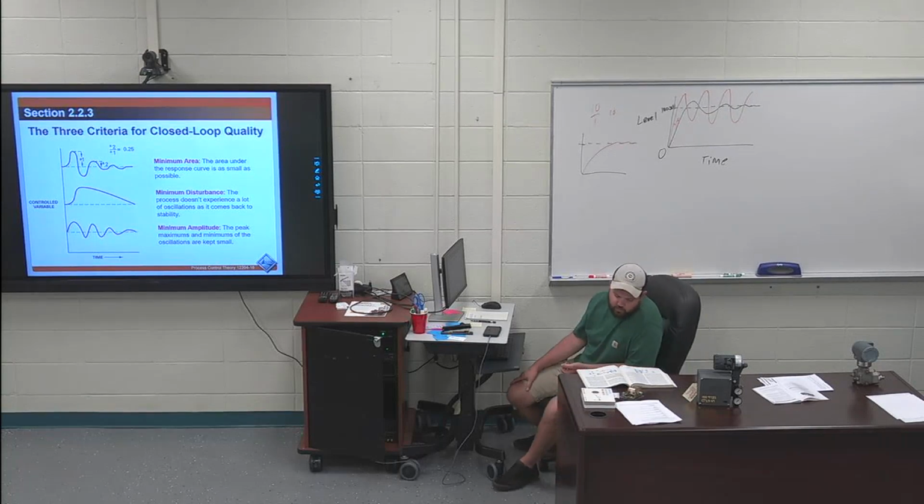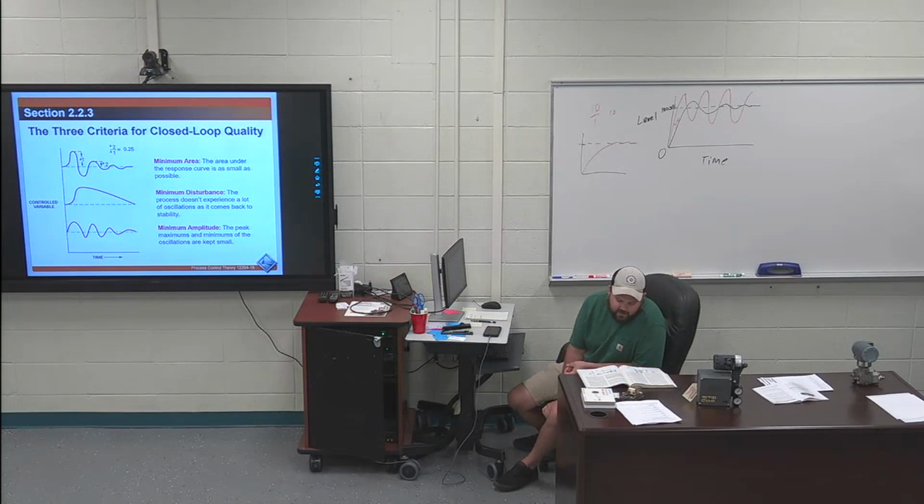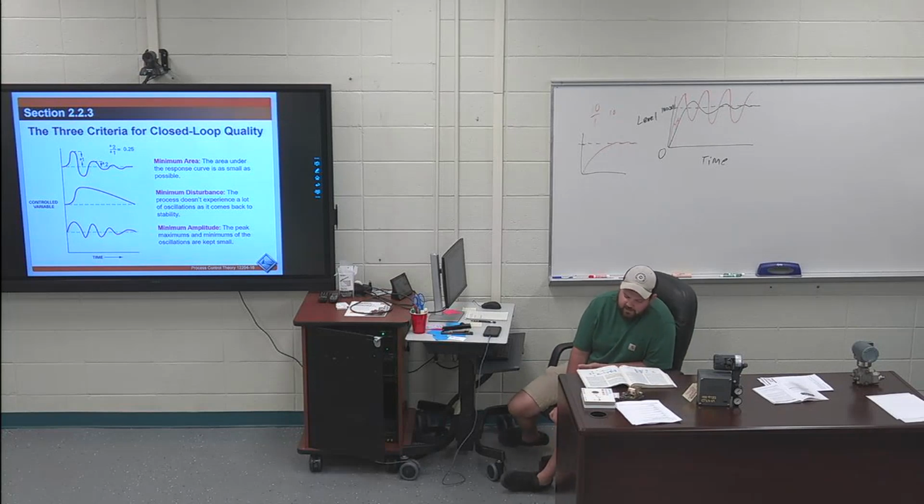And the last type of control, ratio control. The first 2 sentences are one of the highlights. As the name implies, ratio control is maintaining a fixed ratio between 2 or more variables. Most common application of ratio control is maintaining a fixed relationship between 2 flows, such as a mixture of air and fuel for combustion control.